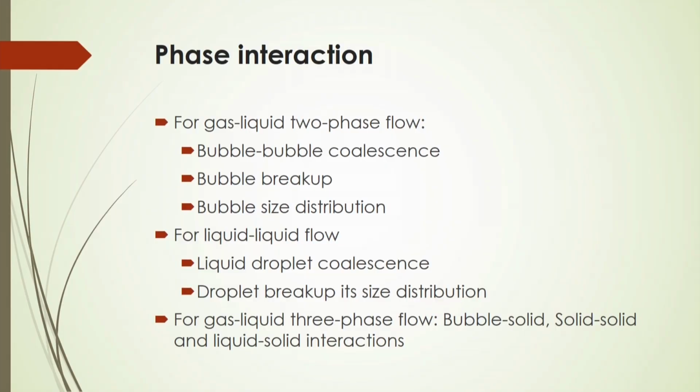Now, phase interaction means, if you are considering gas liquid two phase flow, there will be bubble coalescence, bubble breakup, and bubble size distribution. Even if you are considering liquid flow systems, there will be liquid droplet coalescence, droplet breakup, and size distribution. For gas liquid solid three phase flow systems, there are bubble, solid and liquid interactions. So, in this case we have the interfaces between the phases as bubbles or droplets.